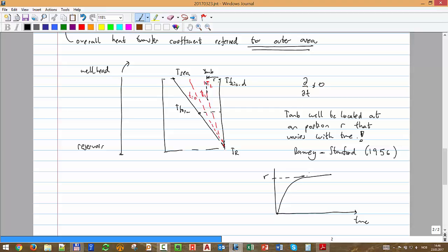Sometimes the simulator asks for which time you want it. For us, if we're going to make studies of the life of the well, you assume that it always reaches that very quickly. But if you're doing, for example, well testing analysis, it might be relevant to know exactly which day of production you are on.